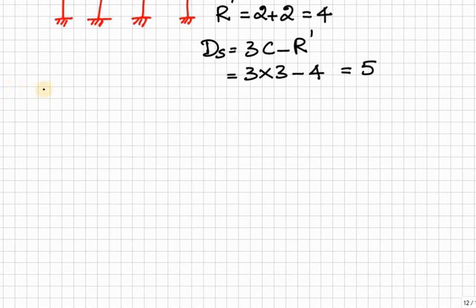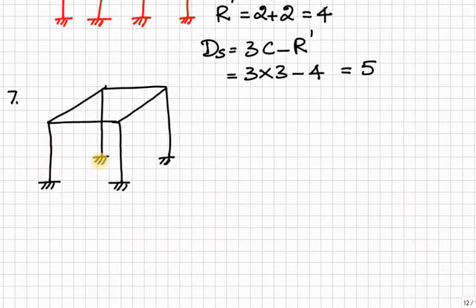Now we will see some example in space, that is space frame, 3D structure. So 4 fixed supports, and the expression is somewhat different here. We'll see some of it a little bit later. Now we have only one closed loop, therefore A is equal to 1, R is equal to 4 times. Here this is space, therefore not 3 reactions per support, but 6 reactions.